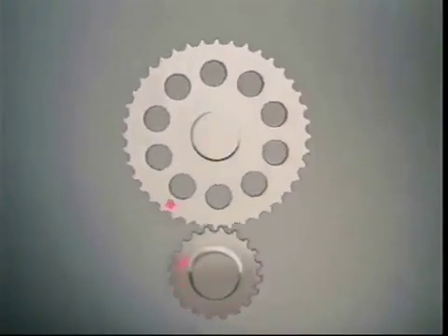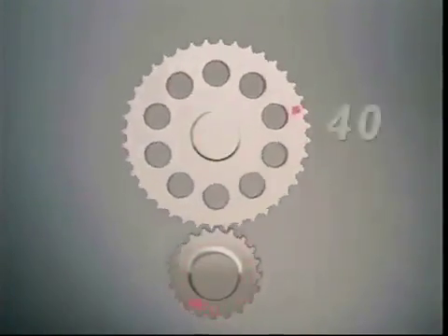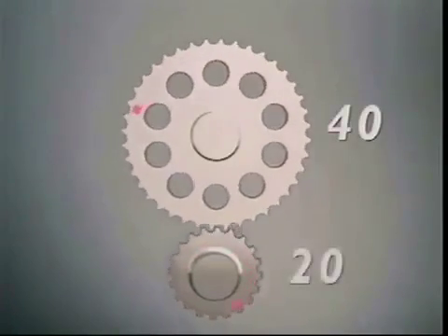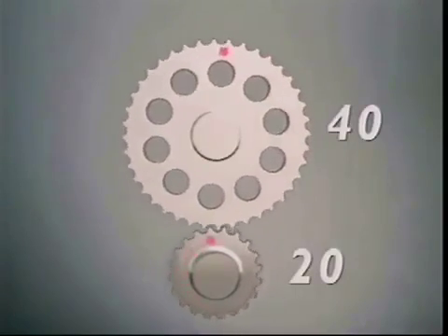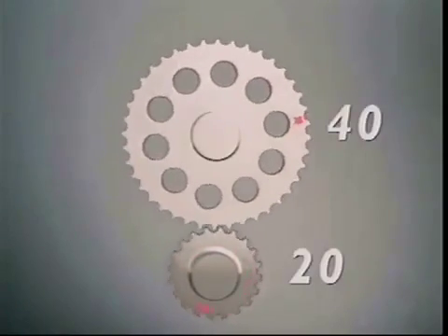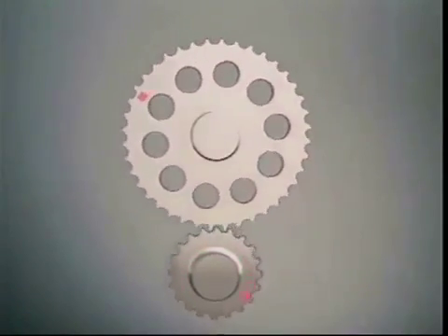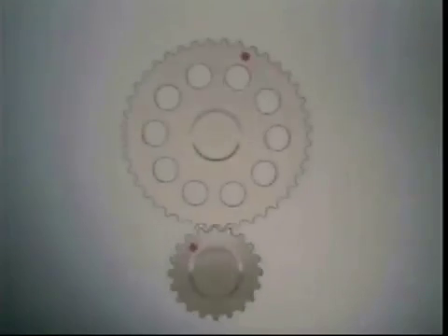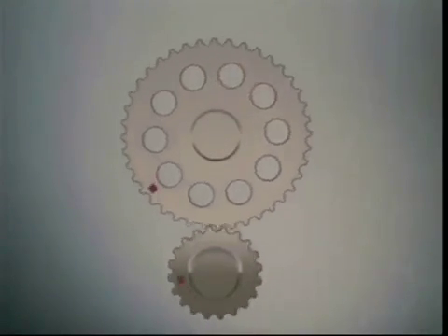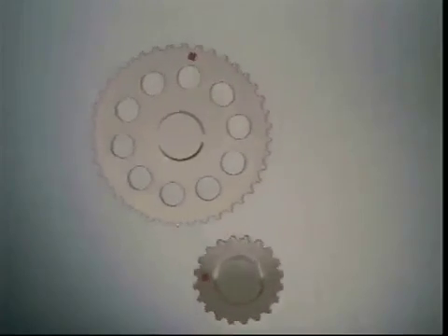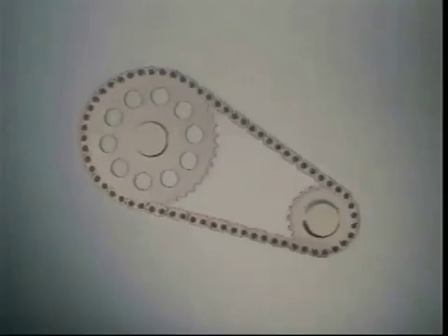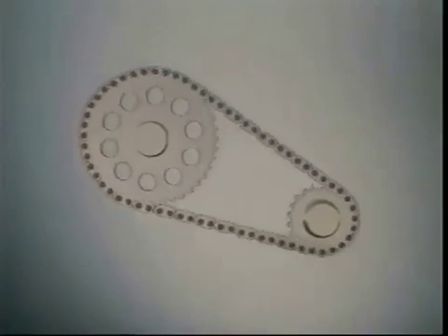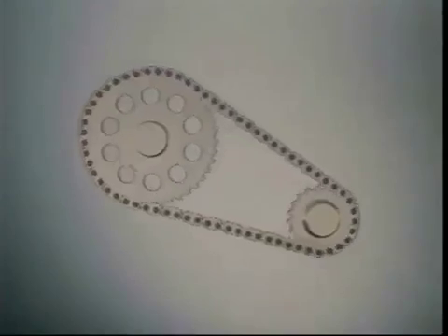Take 2 gears with teeth the same size, one with 40 teeth and the other, the driving gear, with 20. When they mesh, the larger one rotates at half the speed of the smaller one. The gear with twice as many teeth turns at half the speed of the other. These gears turn in opposite directions, and the one with fewer teeth rotates faster. Now let them be separated but linked by a chain. They turn in the same direction, at the same speeds as when they were meshed.